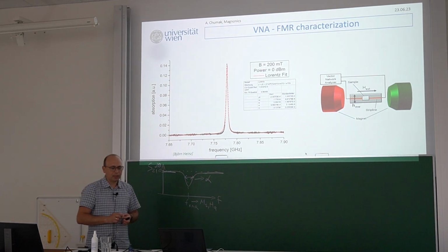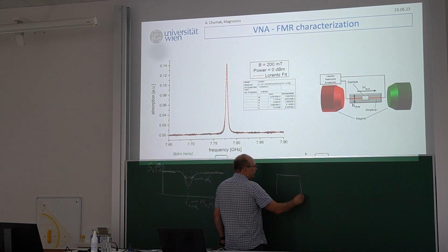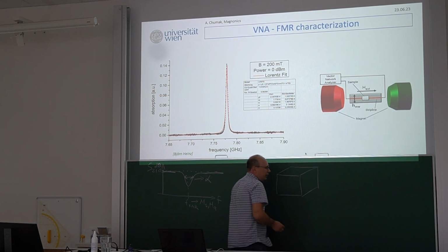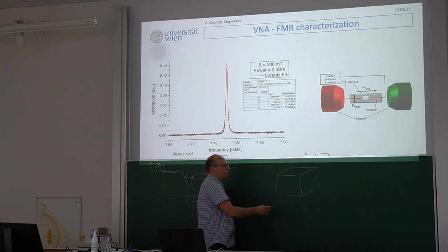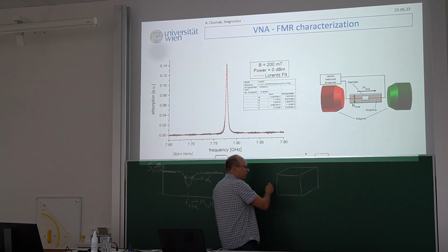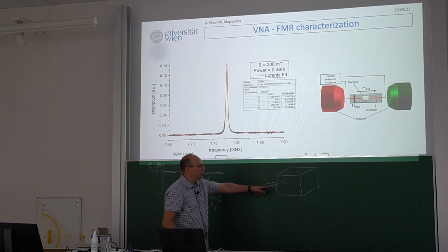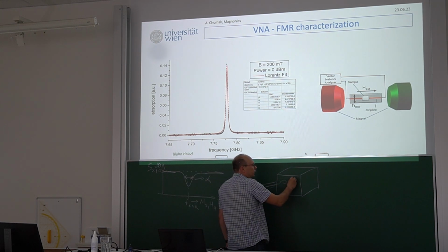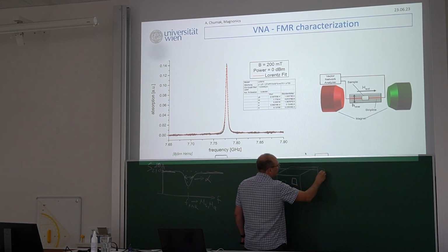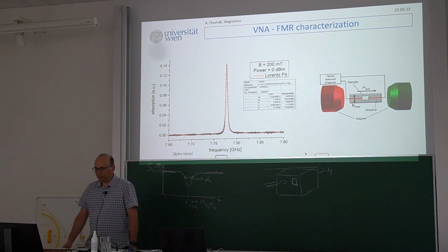In the past, classical ferromagnetic resonance was done differently. People used a cavity. So you remember our waveguides, these rectangular waveguides. More or less you just take part of that waveguide and add 2 walls in there. So there will be some field distribution. There was some trick how you couple this cavity to a coaxial cable, for example. You put your sample somewhere in the middle, and then you magnetize it. And this is the classical ferromagnetic resonance measurement, which was done before.